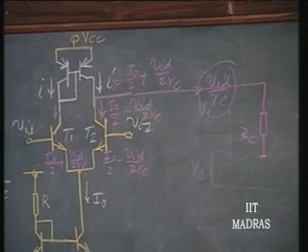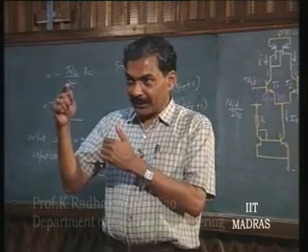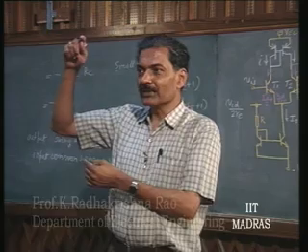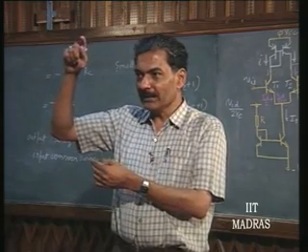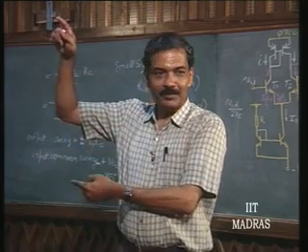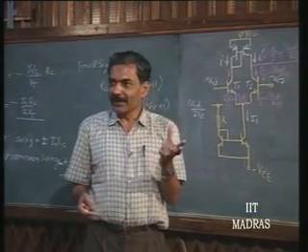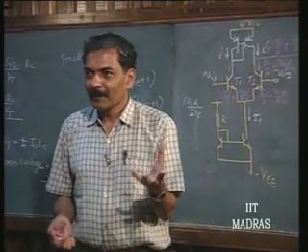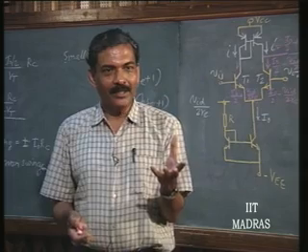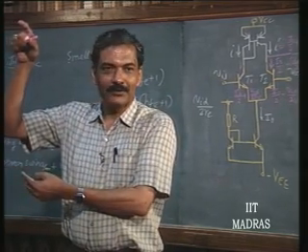That means, in the single ended output you are taking, you are getting back the differential gain output as the single ended output. So, this is a method of converting the so called differential output into single ended output. So, using a current mirror has resulted in not only improvement in the common mode swing capability, but also has resulted in the differential output getting converted into single ended output.